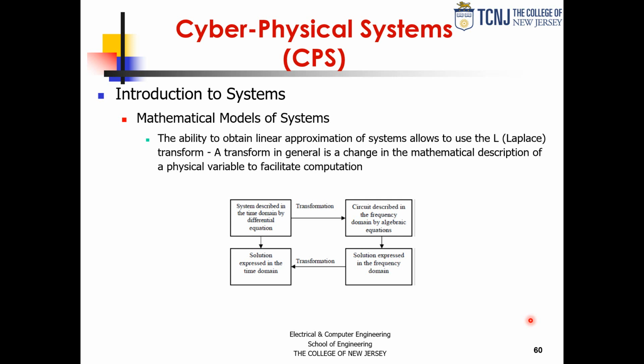That would take hundreds of cycles or taps if you were going to analyze and implement that in the time domain. But if you were going to do it in the frequency domain, you take an FFT, get the spectrum, pick the band out of the spectrum that you want, zero everything else out except the band that you want, and then take the inverse FFT, and then you have your response.